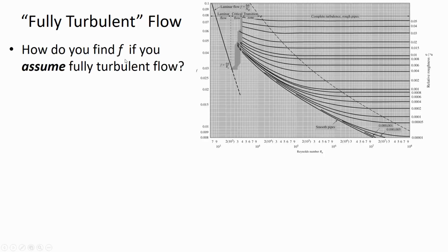So it means that once the velocity is pretty high, once the flow is turbulent, any additional turbulence or any additional velocity is not going to have an effect on the F value. So we call that fully turbulent, when there's a threshold beyond which any additional turbulence does not affect the F value. This is one of our shortcuts sometimes when we have to guess an F value.